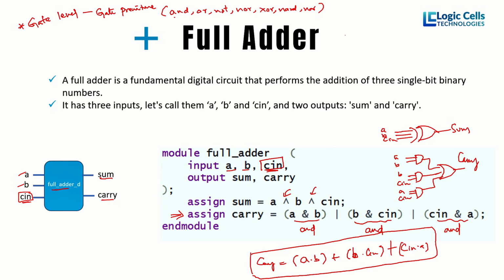You can directly use an AND gate if you want an AND gate functionality for any simple inputs, A and B, providing output Y, let's say variable Y here, and A, B inputs. So the rule is first you need to provide the output, then we need to provide the inputs. These are gate primitives, the gate level description if you use them directly.